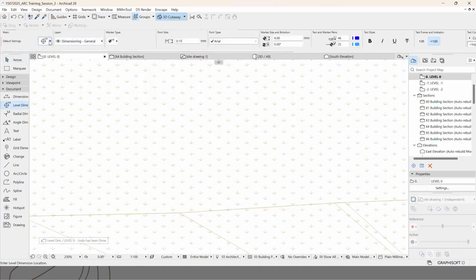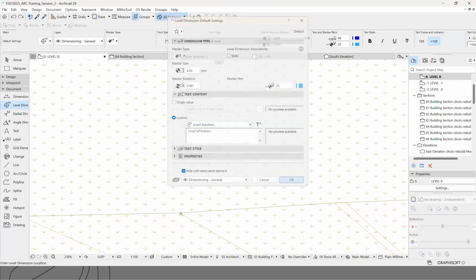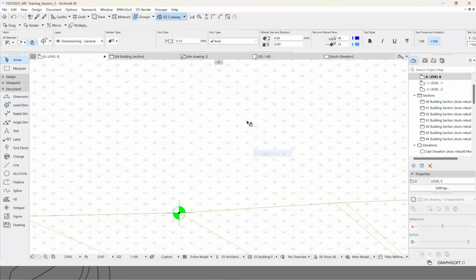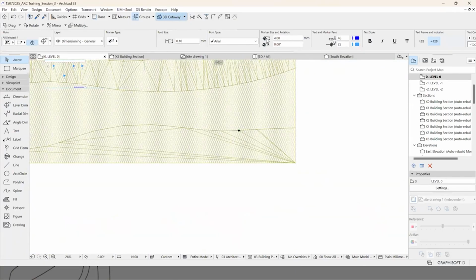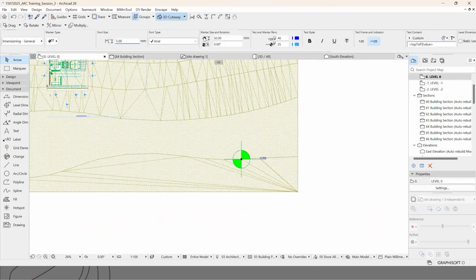So if I go to the settings and make sure I select the right type. You can also give these properties here, whether you want it static or parametric. So we are going for parametric, not static. Which type you want, you can select that, and you make sure you click on the right element here. And display order being different. What is the text size? This is too big. This will increase to 15.